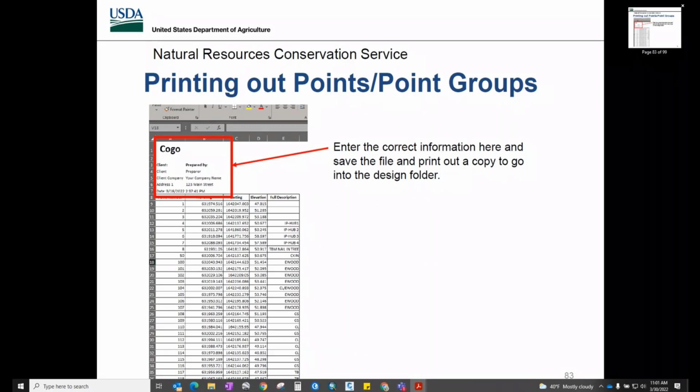Okay. Yeah, and that was just one question that I had, because in Cecil County, we have a hybrid system. So we have the robotics along with the GPS, and you'll notice in this survey that we checked back in on this point 50, and that point 50 was our IP hub 1. So it was 50.677 and the check-in was 50.675. And I know the old school way, when we were doing the total station and a self-leveling level or dumpy level, whatever you want to call it, we had to do a formula. And if anybody's taken Ken's Wolf survey class, you had an allowable error that you could do. And I don't know how that happens in the electronic world of things, I guess, is my question.